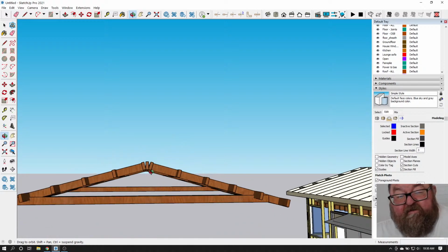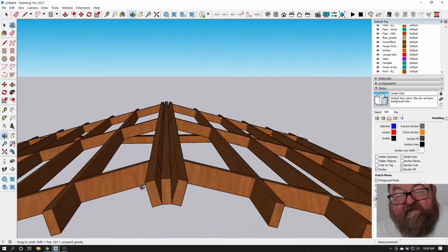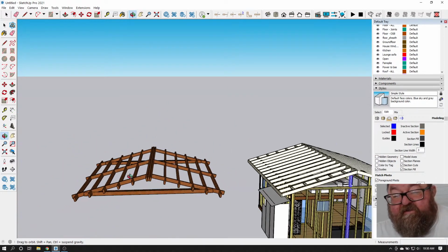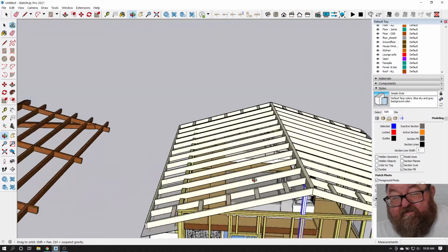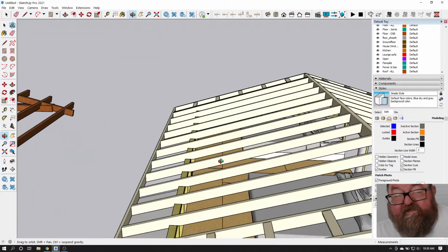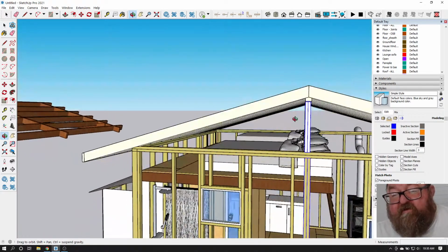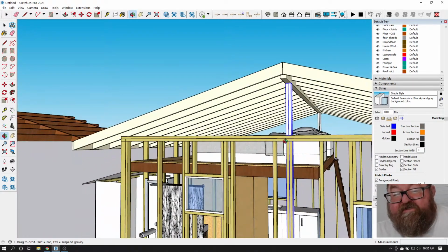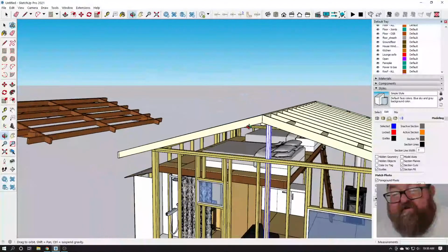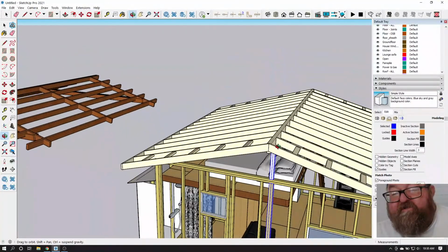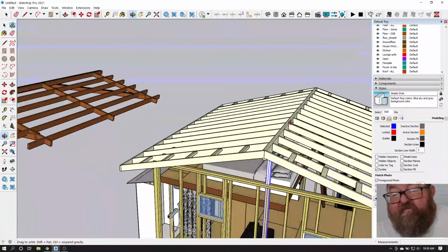Right, so you see what we did was we solved that issue. If these are your rafters, we said these are our rafters, and we don't want collar ties, we don't want ceiling joist. So what we have to do is take care of the structural issues, which we did with a beam, okay?